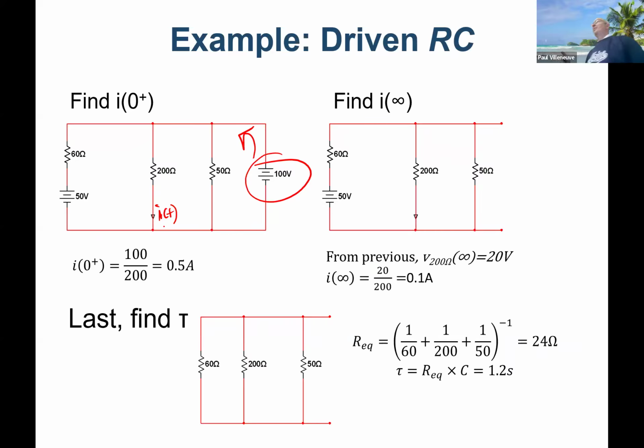Okay, that's really important to make sure you understand the process, is that I've got to go ahead and calculate the initial condition for the voltage first before I can calculate the current. I cannot calculate the current otherwise, or accurately calculate it, maybe is a better way to say it.